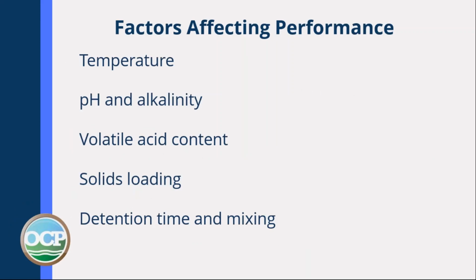Factors that affect performance are temperature, pH and alkalinity, volatile acid content, solids loading, and the detention time and mixing in the digesters.